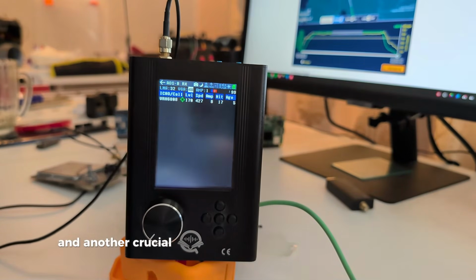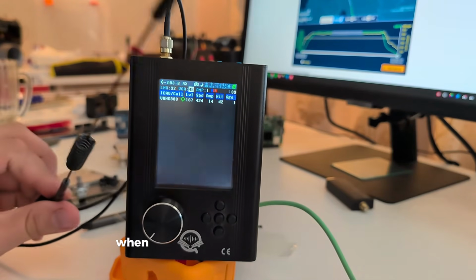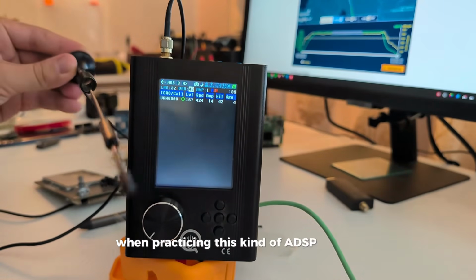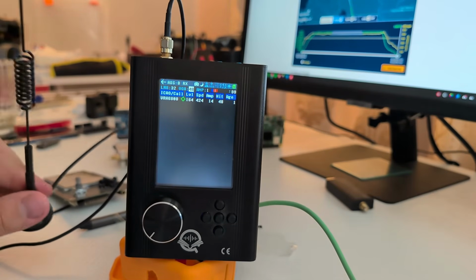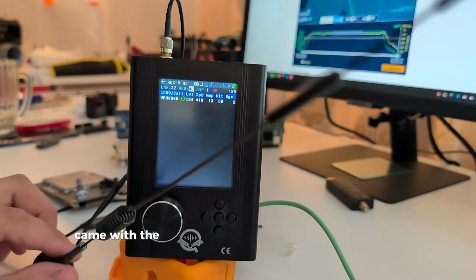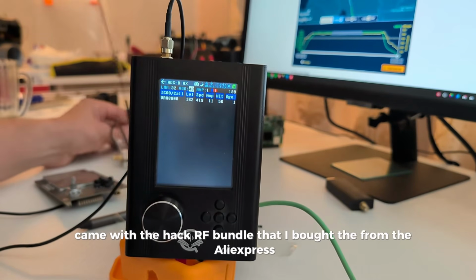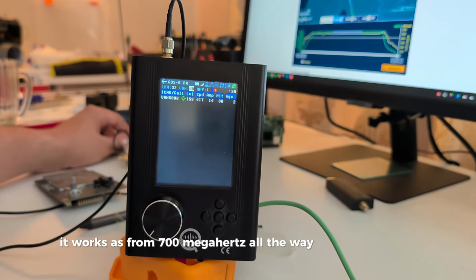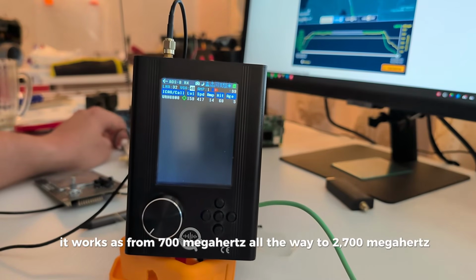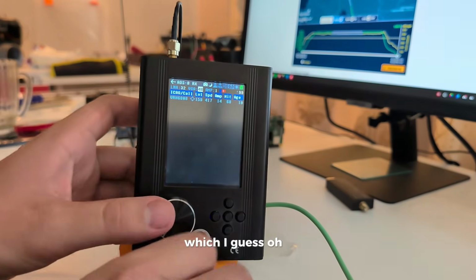Another crucial thing I want to talk about is antenna choice when practicing this kind of ADS-B receiving. You can see the antenna I'm using came with the HackRF bundle that I bought from AliExpress. It works from 700 megahertz all the way to 2700 megahertz, a whip antenna.